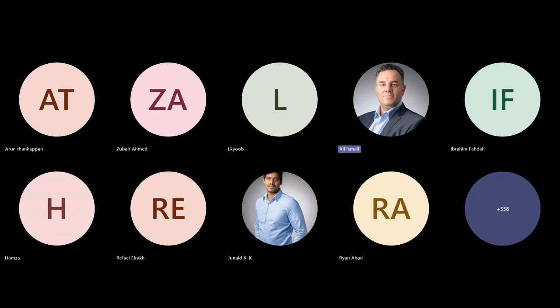Need more clarification on IFC false ceiling. For false ceiling, it is included. We have IFC covering. There is a class in IFC called IFC covering, so you can use it to model the false ceiling and bathroom and kitchen fixtures.